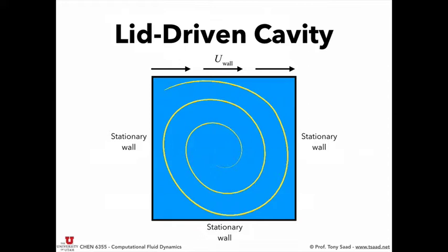The higher the speed, or really the higher the Reynolds number, depending on the viscosity of the fluid, the faster you're going to push these particles over here. And they're going to start accumulating more on the side. They're going to be skewed. But for a high viscosity fluid or low Reynolds number, you're going to have a fairly equal distribution of rotation.